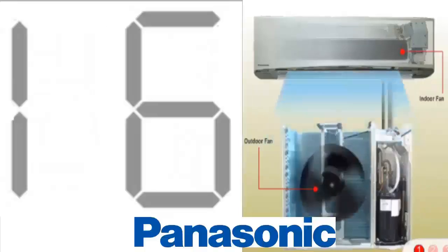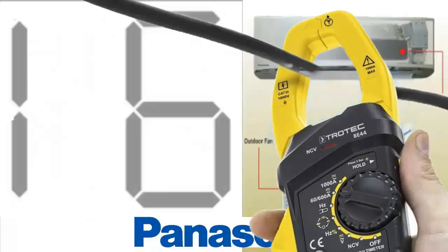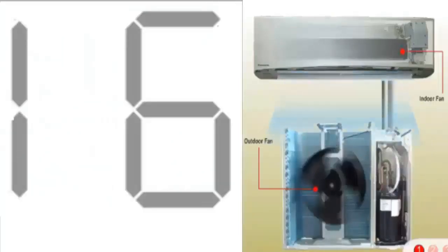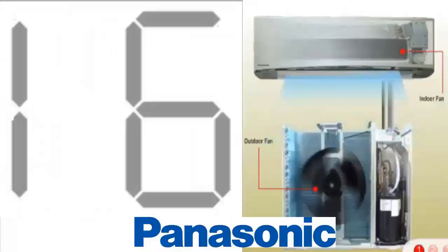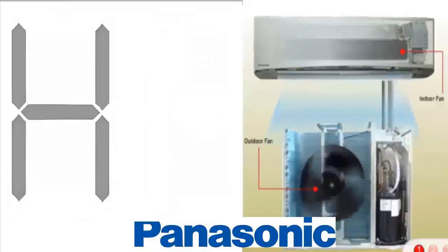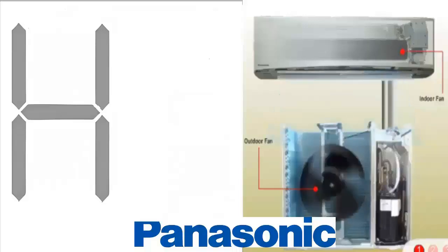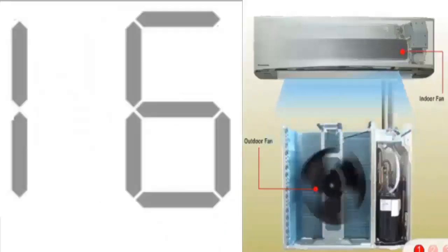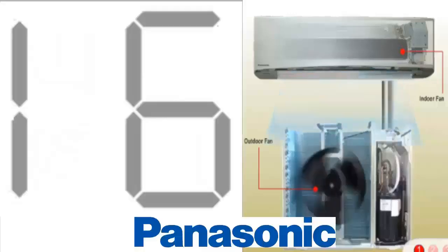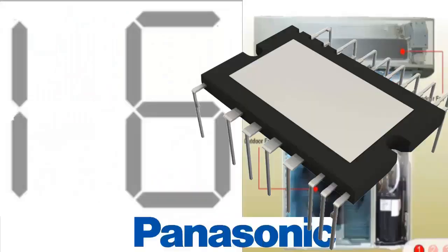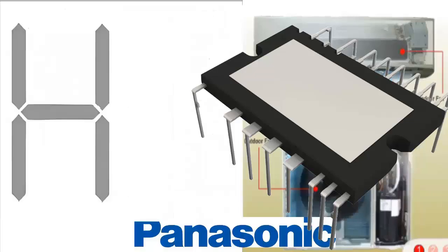1. If the unit stays on for a few minutes, use an ammeter clamp to check if the current consumption is indeed low. 2. If the consumption is really low, but the unit tries to operate, check for oil stains that could indicate a possible refrigerant gas leak. 3. Finally, if you have not found the fault, inspect the components of the outdoor unit's electronic board, verifying connections, and focusing on the IPM Smart Module, whose diagnostic procedure we will review later.